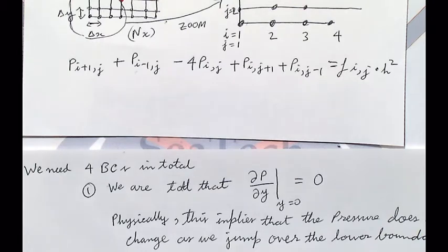Again, what do Dirichlet and Neumann boundary conditions mean? A Dirichlet boundary condition means I'm holding this side at 100 degrees. A Neumann boundary condition might say the derivative is equal to 0 on the other side. What will happen to the temperature in the rod? There is a linear conduction. There's an equilibrium. If I specify a zero Neumann boundary condition on one side and 100 degrees here, slowly the temperature will increase, right?